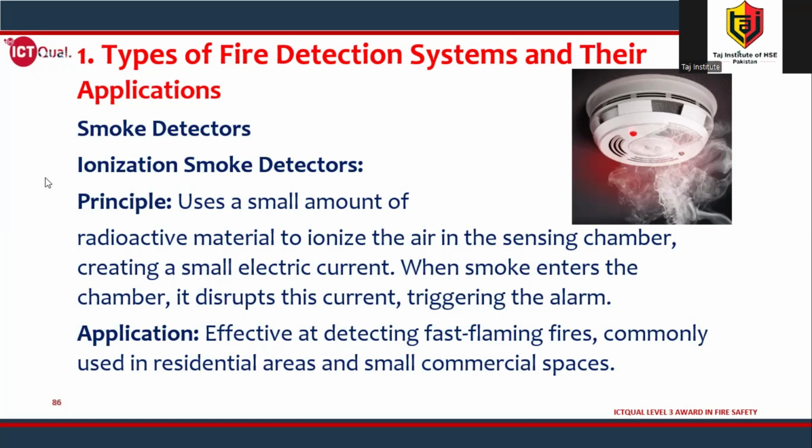Smoke detectors, ionization smoke detectors. You are looking at a smoke detector in the picture. It uses a small amount of radioactive material to ionize the air in the sensing chamber, creating a small electric current. When smoke enters the chamber, it disrupts this current, triggering the alarm.